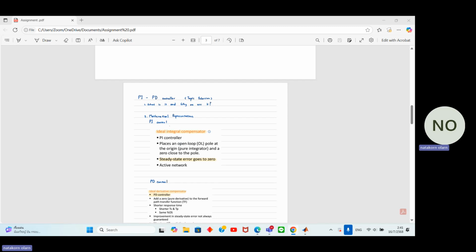So the next one is I, which means integral control. Integral control is a second form of feedback control. It is often used because it is able to remove any deviation that may exist. I controllers are much slower in their response time than P only controllers because they are dependent on more parameters.